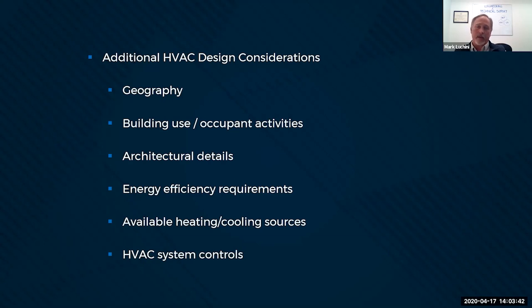And in Bermuda they do it one of two ways. Because it's a limestone outcropping in the middle of the ocean, it's very porous. Depending on how close to the water they are, if they're more inland, they'll use deep wells, and that water is constantly being flushed through that porous sponge that is the island. But if you're right on the ocean, a lot of times they'll run pipes out 300, 400, 500 feet, and have collection ports. So the system still works because you're looking for a 10-degree spread.